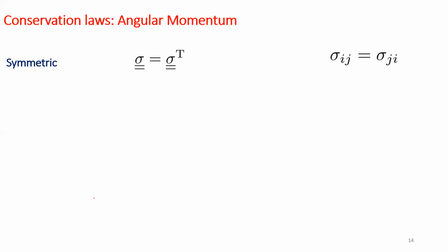symmetric. It's a second order. Now stress is a second order symmetric tensor. Previously, until now, it was only a second order tensor, so it had 9 components. Now, because the stress is symmetric, you have sigma xx, sigma xy, sigma xz, sigma yy, sigma yz, and sigma zz. And these terms again become sigma xy, sigma xz, sigma yz. So you now have 6 components of stress.